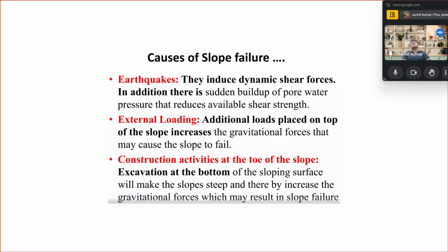As you see, slope failure, face failure, base failure, toe failure: some of the important types of failure are presented. If we disturb the slope, specifically at the toe section, the soil properties get affected and it weakens that section, leading to the flow of soil from there, resulting in failure of the slope.